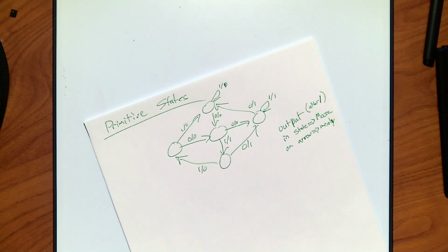So Mealy machines, their output depends on both state and input. But input can have all kinds of weird fluctuations and timing. So your output copies all those weird inputs and timing. So they are not as stable. Mealy is not as stable as Moore is. So that sounds like Moore is better, right? Moore ends up making bigger machines. It makes more states, because to handle all the input varieties, you need more states. That's not what the name came from originally, but it's helpful to remember, right? It's abusing some dude's name, but it's at least helpful.